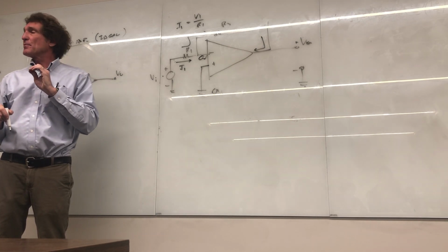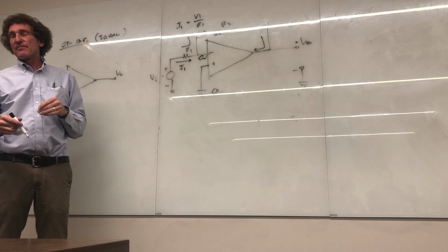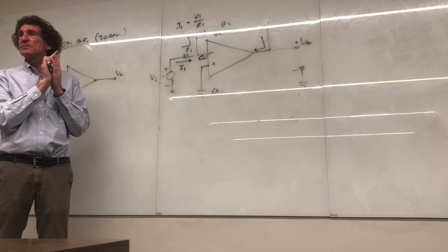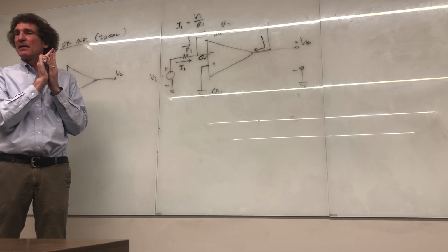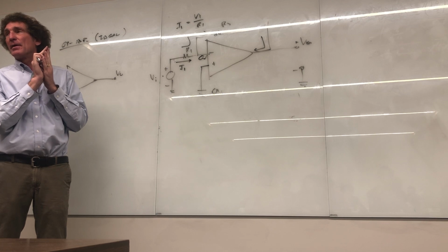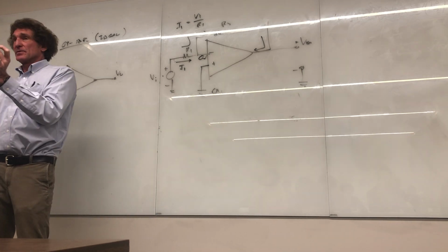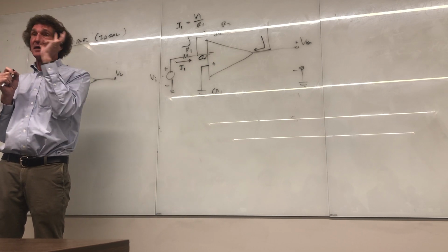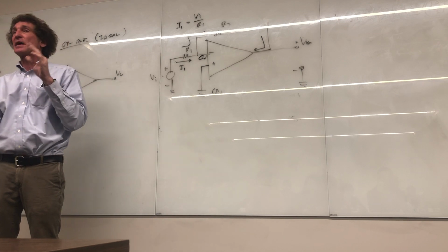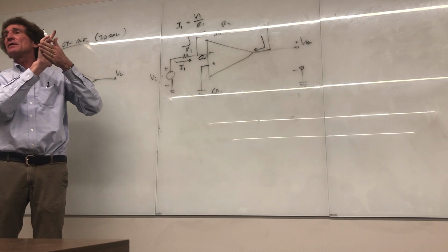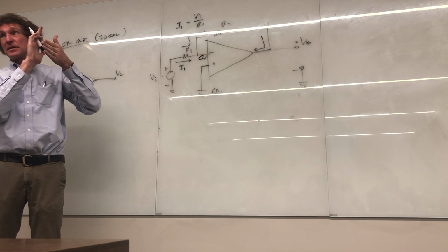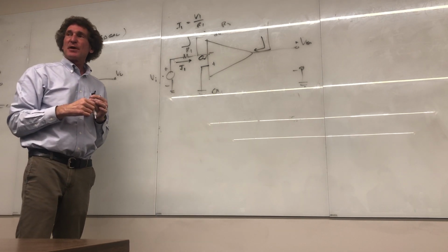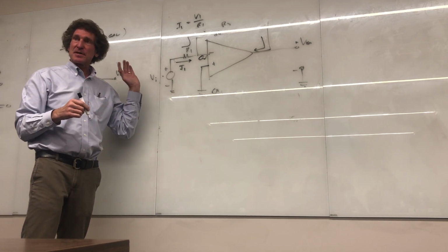Got it? By the way, the input is basically an FET, a field effect transistor, CMOS. You have CMOS right now, don't you? Don't you have Dr. Newton? Hasn't he gone through it? We haven't talked about it yet. We're getting there. Well, you know what a capacitor is, right? How much DC current can go through a capacitor? Zero. None, right? It's an insulator, correct? An ideal insulator. Same with these things. The FET is basically the gate, the driving voltage on that thing is basically a capacitor input. I'll spend more time with this later, but I wish you had your device courses first because then it would make a lot more sense.